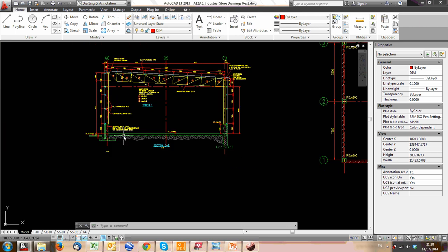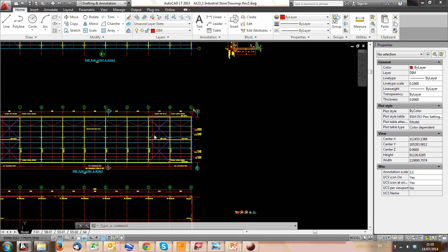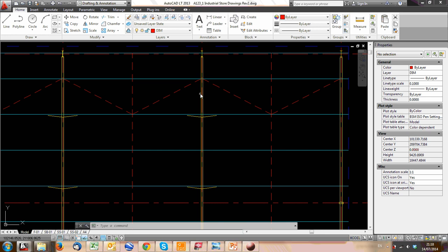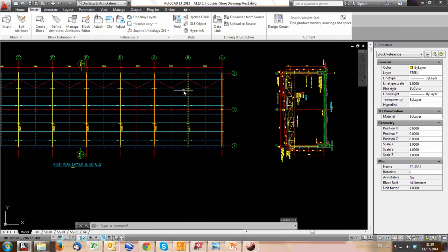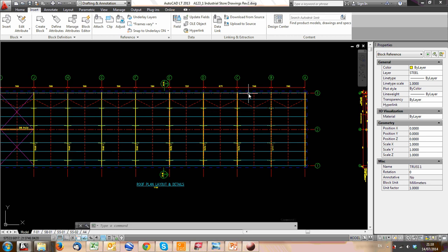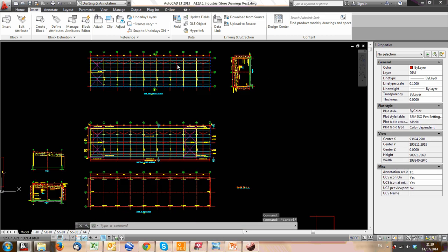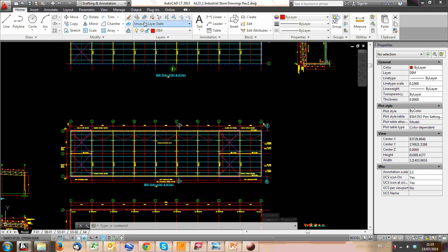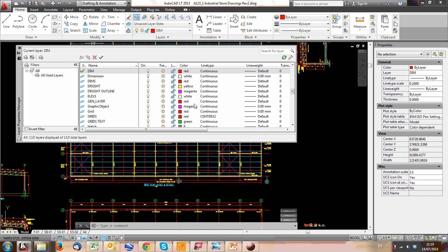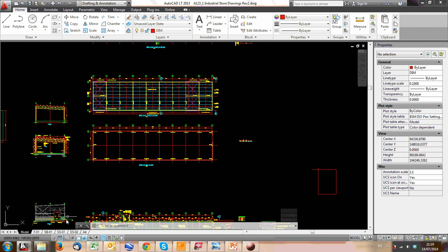We've gone through hatching, we've gone through projection lines, gone through blocks, how you create a block, how you insert the block, how you edit the block by double clicking on it, creating arrays and the likes. In the next one we're going to start using layers more. We had a bit more of an introduction to our layers, turning layers on and off and editing those. And then we're going to start getting towards the stage of creating drawing.